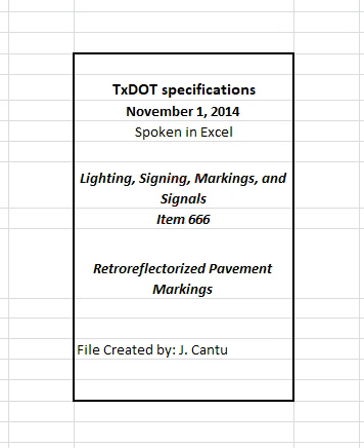It must place linear non-profile markings up to 8 inches wide in a single pass, and non-profile pavement markings other than solid or broken lines at an approved production rate. It must place a center line and no passing barrier line configuration consisting of 1 broken line and 2 solid lines at the same time, to the alignment, spacing, and thickness for non-profile pavement markings shown on the plans.